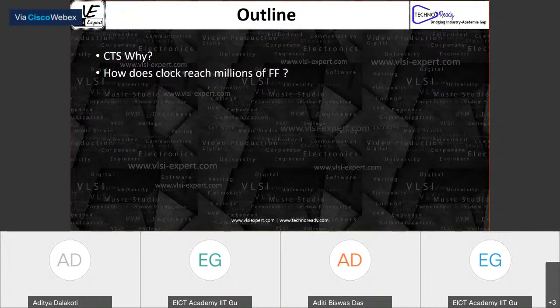There is no good way to predict what is the optimal point. Just letting the tool run blindly is one way of doing it, but it will not be an optimal answer. Tools expect you to be able to guide with what kind of design you want to do. How many buffers, which buffers, what is based on the frequency, how you design the wiring, how you place the blocks, that all has to come from the designer.